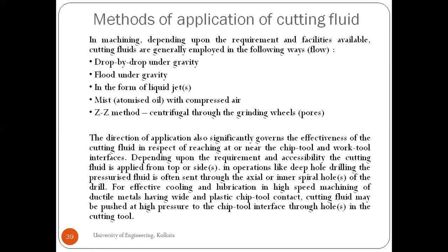Around 70% of the heat is generated at the chip tool interface, 15% at the primary shear zone, and 15% at the work tool interface, that is at the worn out flanks. Please remember this: 70% at the chip tool interface, and the remaining two parts, 15% each, at the primary shear zone and the worn out flanks.